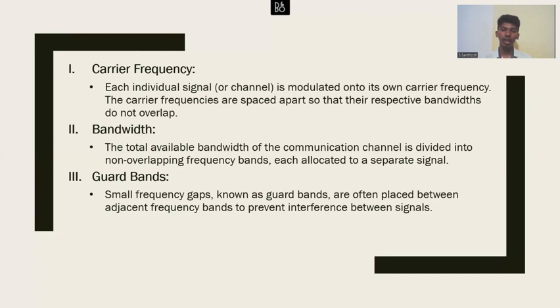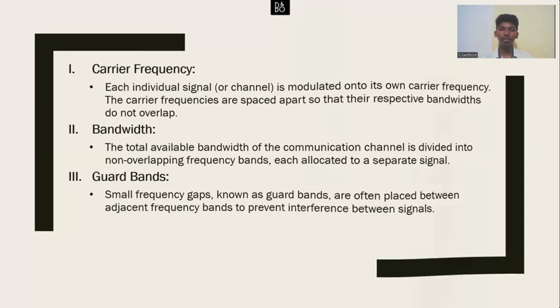It's like a vacuum or a space present between two channels, where you don't use that particular bandwidth or frequency to communicate anything between any sources. Only the frequencies above and below are used, and a certain set of frequency is not being used. And that's what these guard bands are. They just help us to prevent interference between signals.